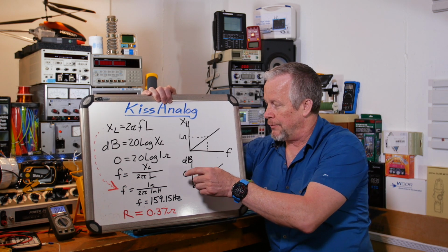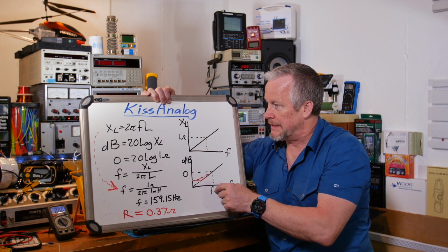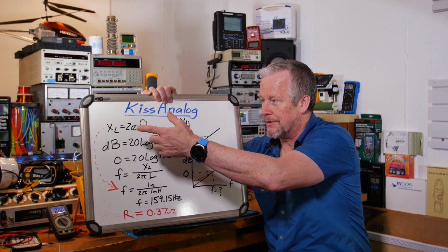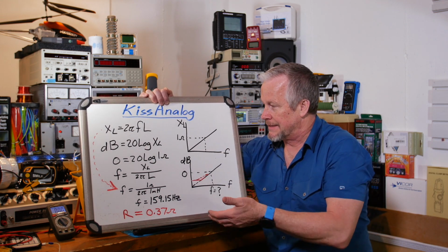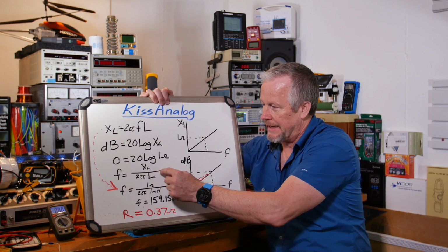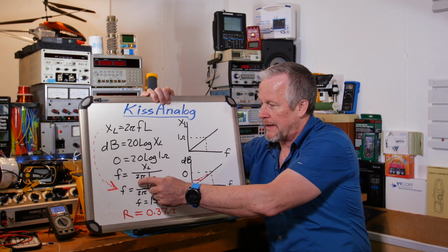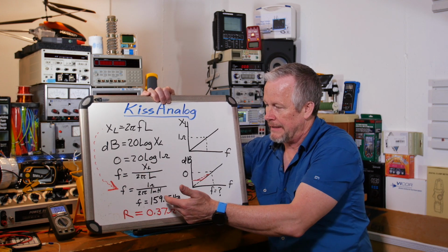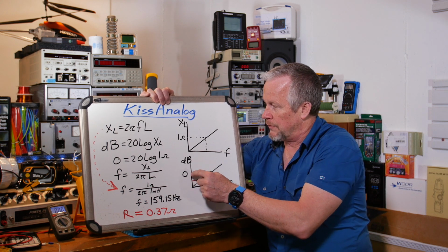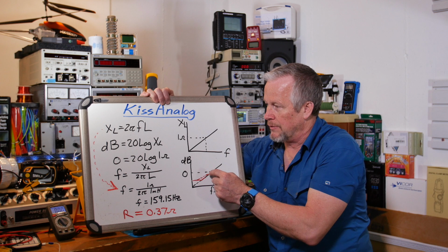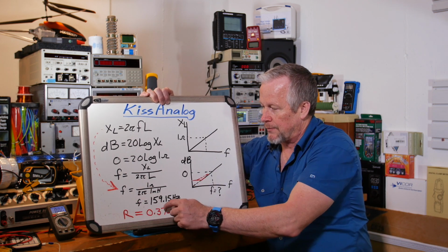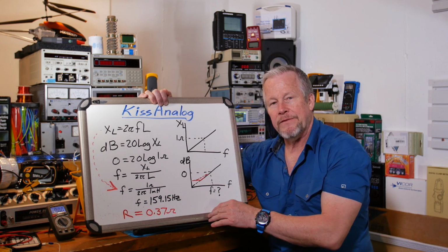So if you graph something, you come over and see the frequency. You can come up here and calculate what the inductance would be, like we talked about. In this case, we're going to change that formula to this formula, this guy. So we're going to say X of L divided by 2 pi L is equal to F, okay? So this stuff right here, we know that we're going to look for the case where impedance is 1 ohm. X of L will be 1 ohm. We know it's a 1 millihenry inductor. So we solve for F. That's going to happen at 159 hertz.